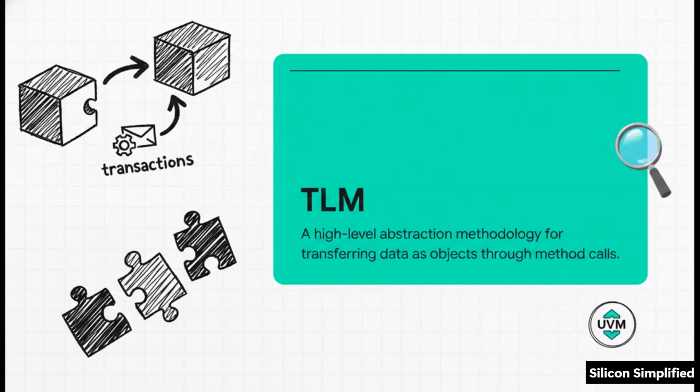Instead of wiring low-level module ports together like the old days, TLM lets us transfer data at a much higher level of abstraction. We basically pass transactions, which are just structured data objects, using standard method calls between our producer and consumer components. This creates a brilliant plug-and-play reusability. You end up writing way less code, your simulations run significantly faster, and you get to maintain completely independent components.